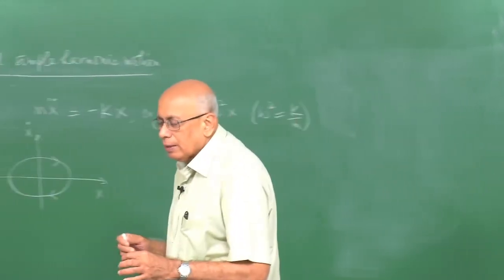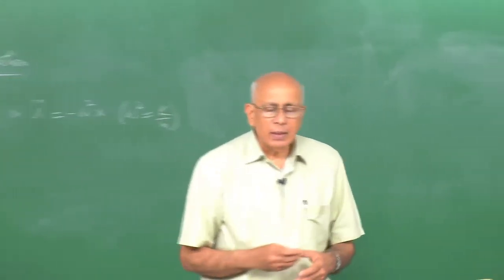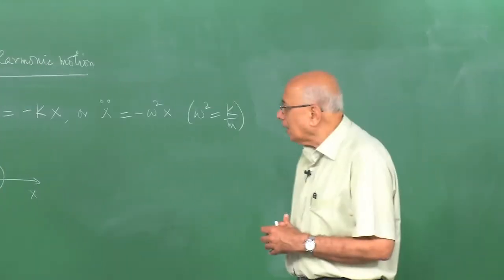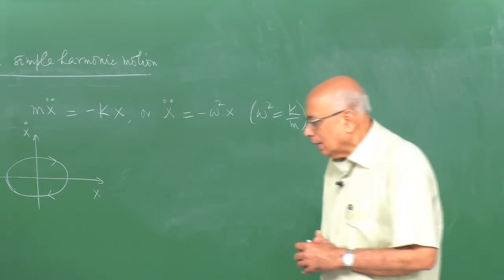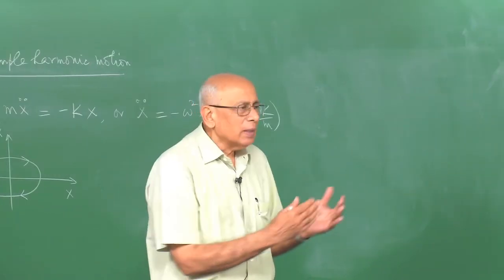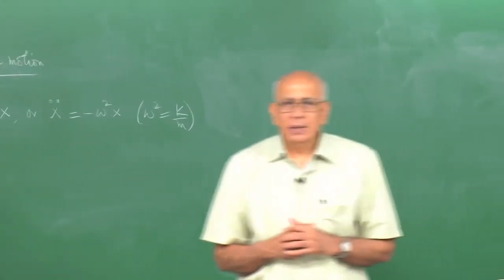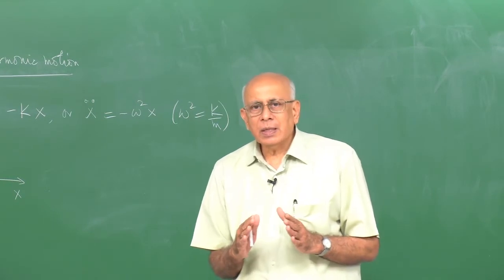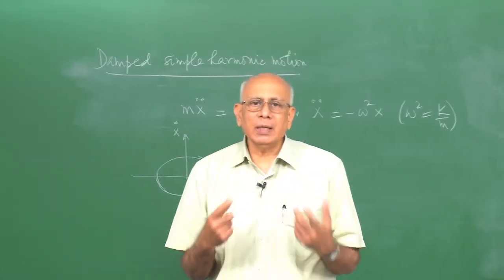It is exactly what happens when you drop an object like a ball bearing inside a dense liquid. Due to the viscosity of the liquid, the particle's velocity gets slowed down. There is friction on this object because of viscosity, and there is what is known as viscous drag or viscous damping, which causes slowing down and dissipation of energy. Just as when you walk through a crowd, the faster you try to go in a particular direction, the more the retarding force, because of the more collisions from the front. In exactly the same way, the viscous damping in its simplest form is a drag force in the direction opposite to the direction of motion, and proportional to the velocity itself.